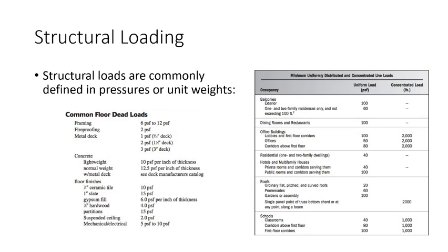So for example, with concrete, we might know concrete weighs 150 pounds per cubic foot, and so we need to multiply that times the thickness of the slab to get a PSF. As an example, if concrete weighs 150 pounds per cubic foot, and I have a 6-inch slab, 6 inches is half a foot, so that's 75 PSF, right? So you might have to do a little bit more of an involved calculation. And then you also got to be an engineer about it.